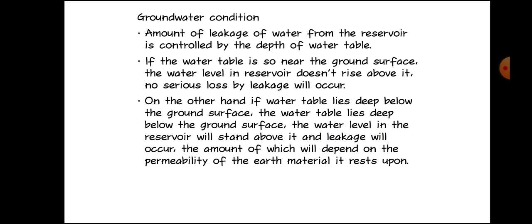On the other hand, if the water table lies deep below the ground surface, the water level in the reservoir will stand above it and leakage will occur, the amount of which will depend on the permeability of the earth material it rests upon.